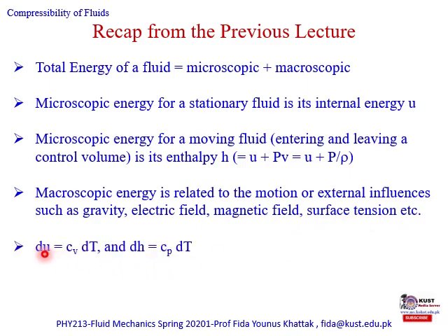The change in the internal energy could be written down as the specific heat at constant volume and the change in temperature, and the change in enthalpy could be written down as the specific heat at constant pressure and the change in the temperature. For incompressible fluids, we learned that the change in enthalpy is equal to the change in the internal energy plus the change in pressure over the density.